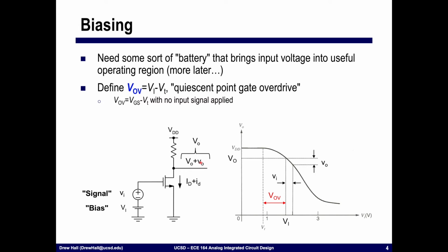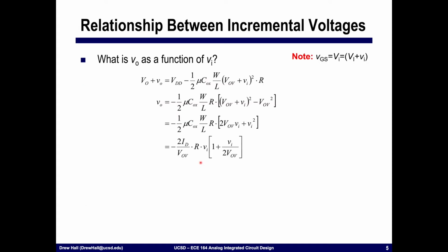All right, so now let's take this to the next step and let's derive a relationship between the input and the output voltages. Okay? But rather than just look at the small signal voltages, I'm going to include the DC bias, and I'm explicitly going to break this out. Okay? And so what I mean is that at the input, I'm putting that we have an overdrive voltage plus our AC voltage, and similarly at the output, I will have a DC voltage plus a small signal voltage.